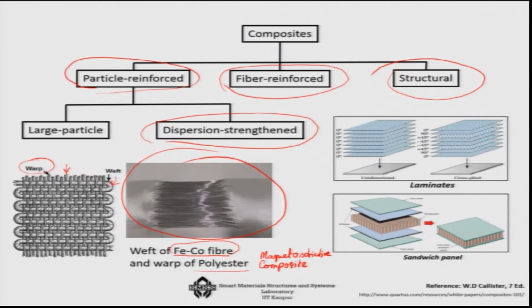Now, in the form of the structural composite, we build up the layers of the composites. If we keep all the layers with the same fiber angle, like all 0 degree fiber angle, then we call it a unidirectional composite. If we vary this, 0 to 90 etc., then it can be angle ply, it can be cross ply. If it is cross ply, then it is generally only 0 and 90, and if it is more than that, like in this example, then it becomes angle ply.